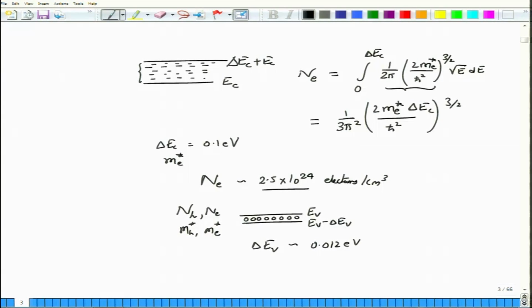And the implication that electrons have a smaller effective mass also means that when you forward bias a junction, electrons will move quickly because of their higher mobility and lower mass into the hole region, and therefore in most cases it is desirable to pump electrons from the N layer onto the P side layer.